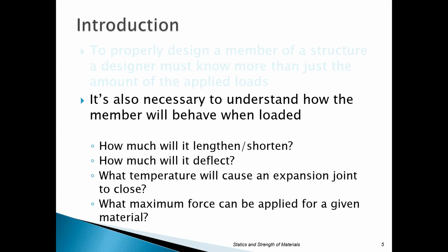Temperature changes can cause problems internally. We get things called expansion or contraction due to temperature ranges and changes. Any bridge that you drive over of any size typically has an expansion joint on one or both ends of it, which allows your bridge to expand or contract with various conditions of temperature. If you don't let that happen, you can actually have things get too compressed. Pavement on a hot summer day can actually explode if it doesn't have expansion joints, because the two sections will come together and basically just compress until it can no longer handle it.